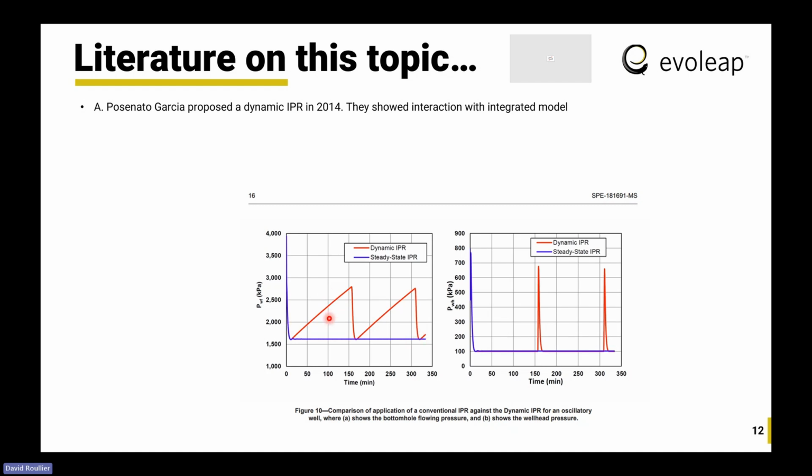Okay, so this is severe slugging, or analogous to severe slugging for the well bores. This is the bottom hole pressure. This would be the wellhead pressure. So this has been observed. This is known to artificial lift people. And it's basically a phenomenon we're neglecting in our flow assurance simulations, okay?